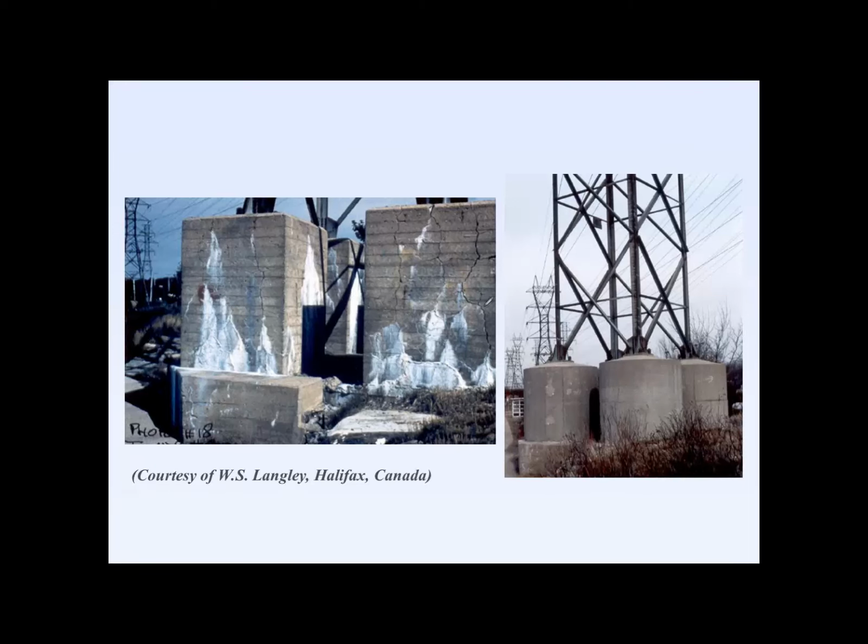Here's some other towers that were repaired as well, and you can see the before picture. You see large amounts of ASR gel and exudation. You see large cracks. And then after the repair and the placement of the external concrete ring, you can see the overall results here.